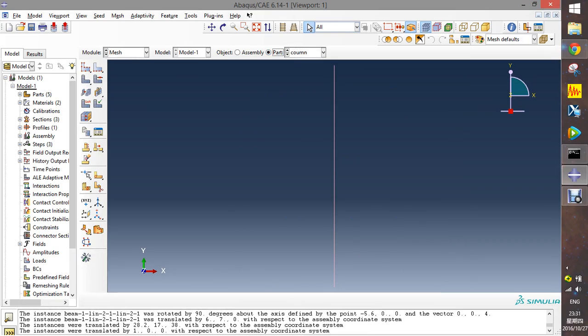And after we mesh the model, we will go back to apply the constraint and the boundary conditions on the node, and also apply the ground motion on the bottom nodes. Here for this part, we will mesh the whole model with parts. After every part is meshed, the mesh of the whole model is automatically generated.